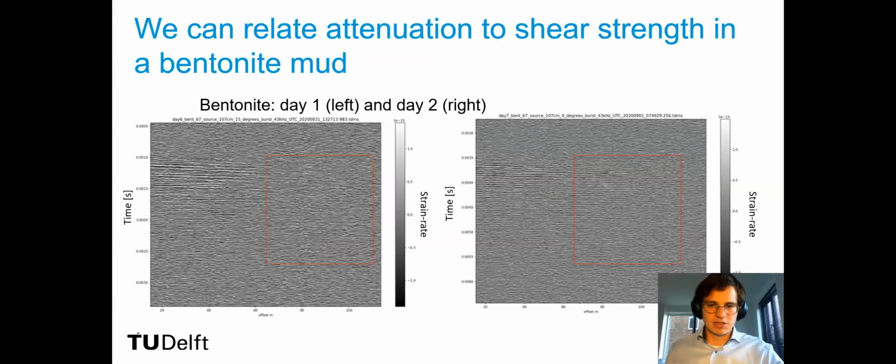In particular, what I was showing before here is a common source gather, where we basically are stepping away from one of the cross-correlation pair channels. And we see this sort of interference when we have an off-axis source or scatter, because the travel time variations are very similar for the virtual source and the secondary source. Whereas here, for a common offset gather, we can basically step along the two channel pairs that are the same distance apart. And this flattens the travel time curve for the direct wave, because the distance is always the same, so long as the lateral variation of velocity is small. And it allows us to zoom into what's happening with the secondary source.